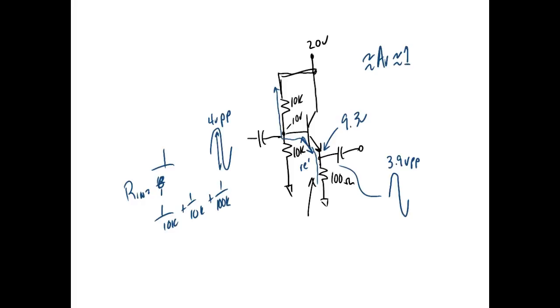So we can have extremely low output impedances on these things. They give us pretty high input impedance and a real low output impedance. These are your current drivers. These are the guys that drive low impedance loads. Low impedance means it's going to need a lot of what? A lot of current, right? You understand that? So these guys give us tons of current gain, but we don't get any voltage gain.